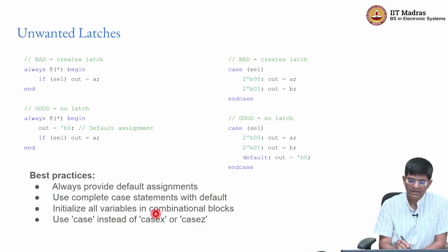And there are a couple of other constructs in Verilog, notably the casex and casez. What those say is that you can actually put in X or Z values to indicate that if, during the simulation, one of those values is unknown or is tri-stated, how should the system behave? Now that's not a good idea. Well, casex could potentially be used in order to simplify your logic a little bit.